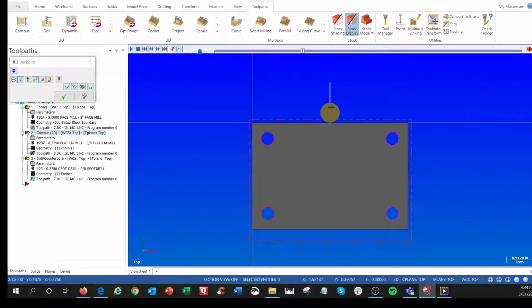And it's going to stay to the left. Now, it knows it's staying to the left because it's looking ahead. So the next move would be this one. We're going to go to this coordinate here, which would be X3, and then add in half the diameter. All right, and then we go to here. This would be Y-2, add half the diameter.